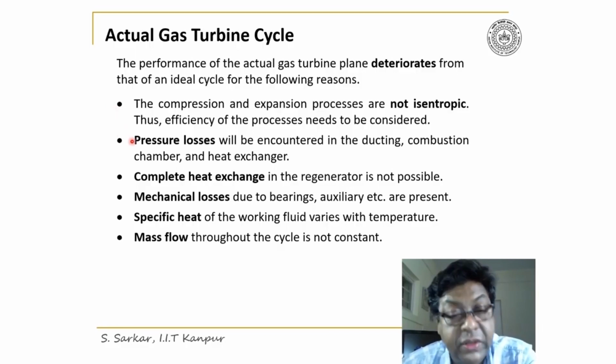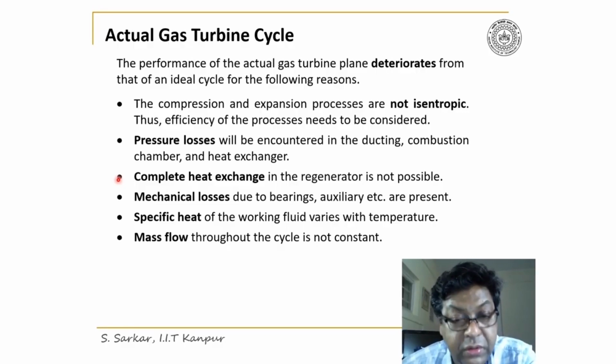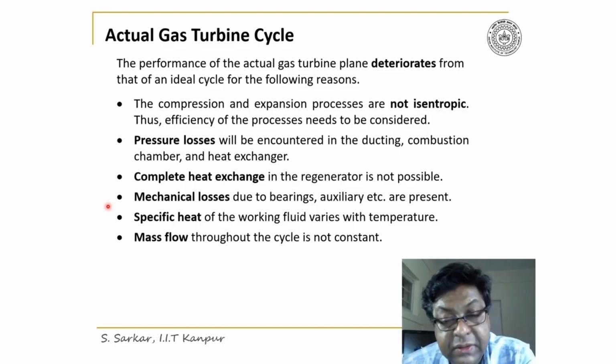Furthermore, pressure losses will be encountered in ducts, combustion chamber, and heat exchanger. Next, complete heat exchange in the regenerator is not possible. Furthermore, the mechanical efficiency due to bearings and auxiliaries must be considered, so there will be some losses.